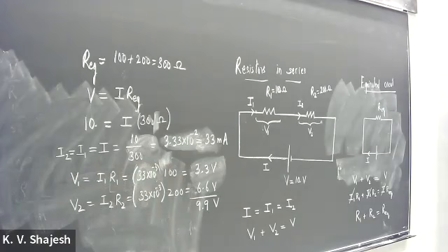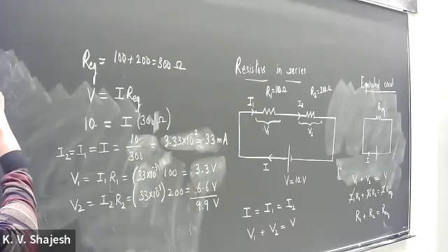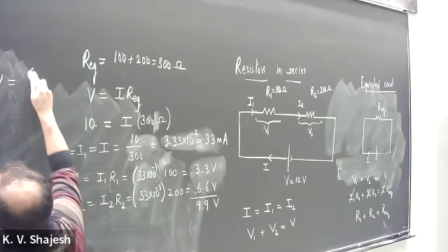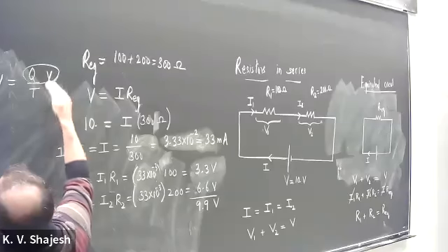So a common usage in electrical circuits is the idea of power. So this is power consumed, and power is energy per unit time. So this would be equal to current times voltage. Notice current is charge over time, Q over T, and voltage is energy per charge.